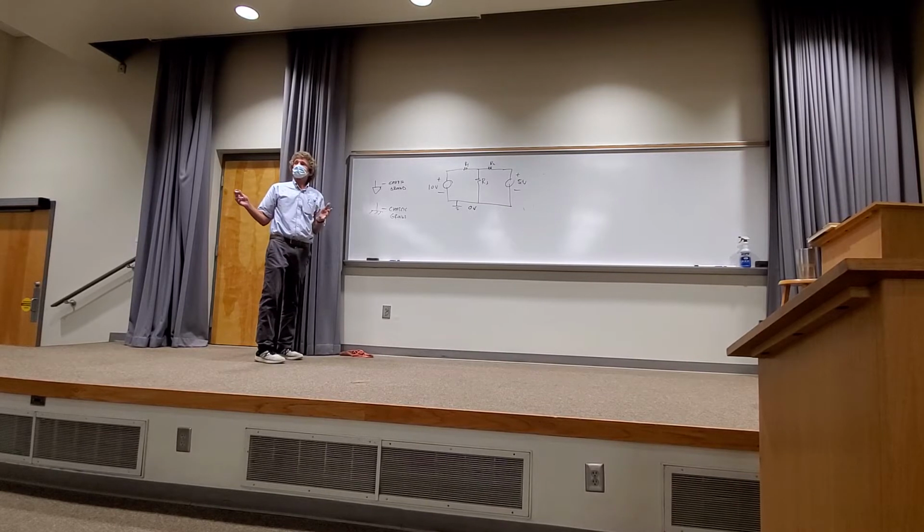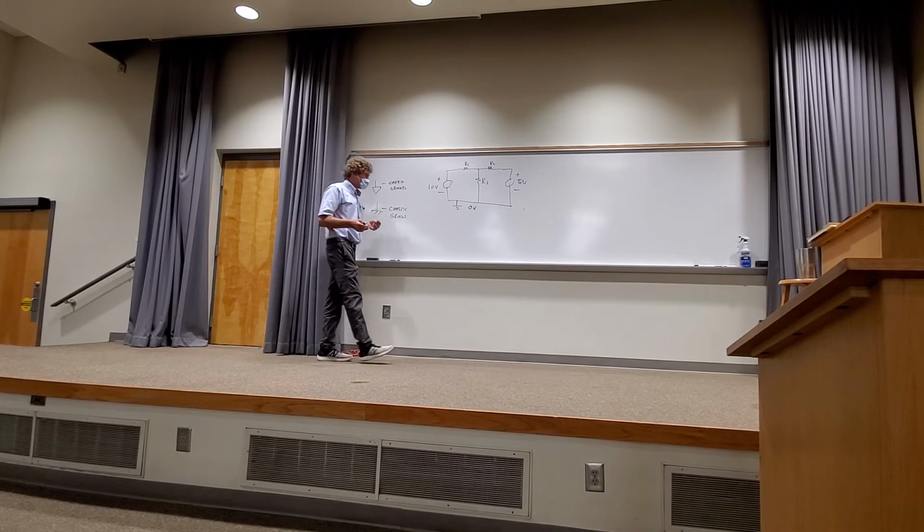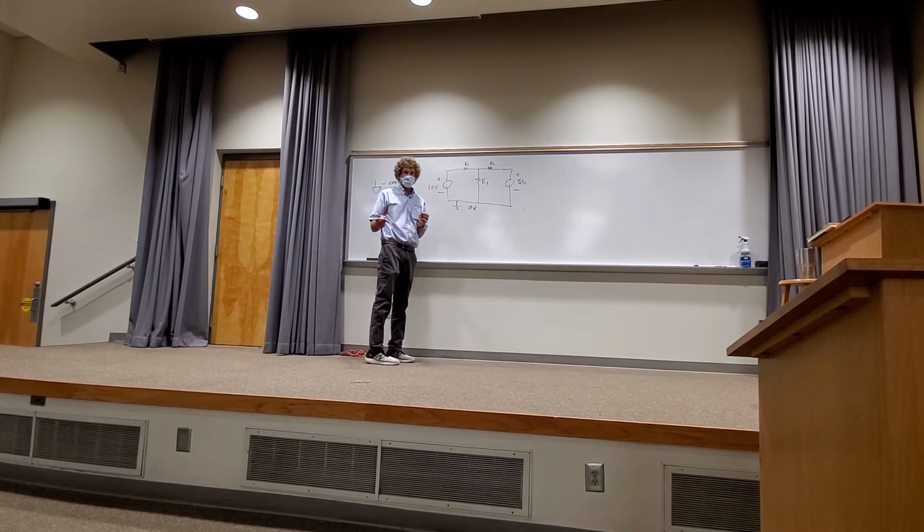If all the grounds had zero resistance leads to the other grounds, there'd never be a voltage difference between them, but there is in the real world. There's a significant voltage difference, for a lot of purposes, between the earth ground and a circuit's ground. It could be of the order of millivolts and even maybe tenths of a volt, which becomes significant in a lot of ways that you'll see later.